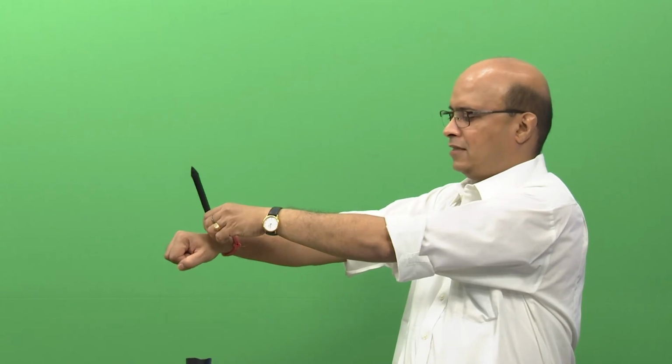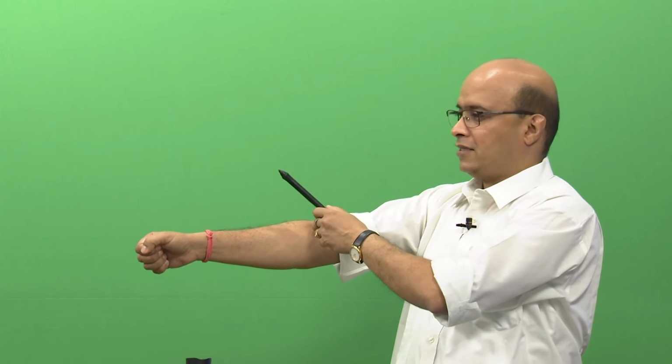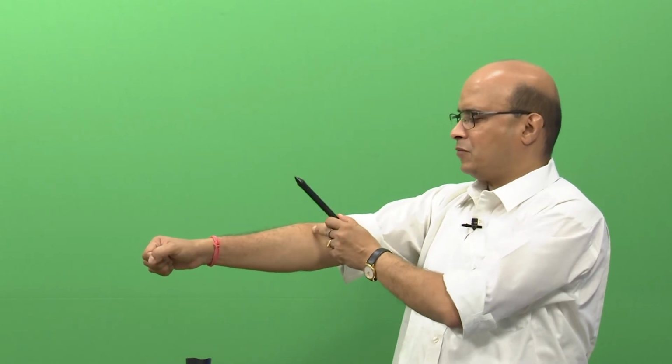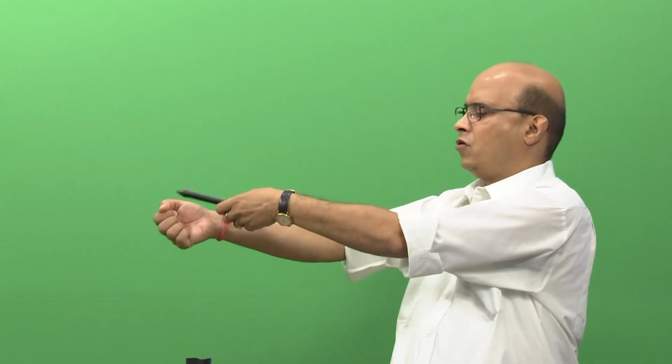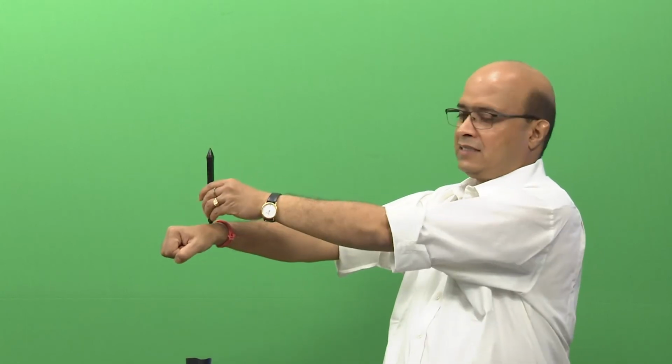Now, in the human hand, the roll axis is from here. Okay, so, we have a combined elbow joint. So, in the human case, the roll axis comes here. Okay. So, in the human, we have a different wrist, where the last 3 axes are not intersecting. Okay. So, please note that in the case of the robot, the last 3 axes are intersecting at the joint, at the wrist, which is my roll, pitch, and yaw. They are all intersecting here. Whereas, in the case of the human hand, they are not intersecting, because we have the roll which takes place